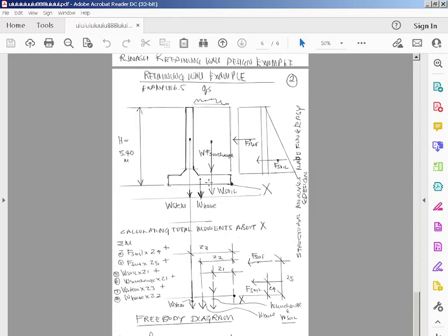What I do in the next video is you do RV. Obviously M equals RV times the eccentricity, so we're looking for pressures, the maximum pressure under the base and the minimum. But this was just a summary of everything, all the moments. This is just a summary I've done of the moments, just to show how everything fits, because the next step is to find the total moments